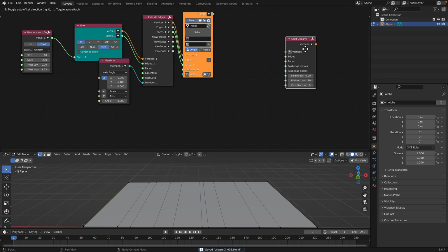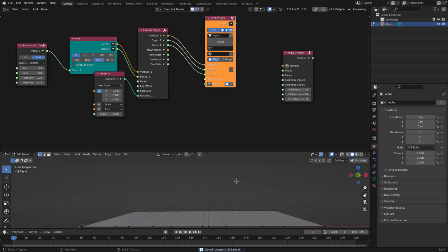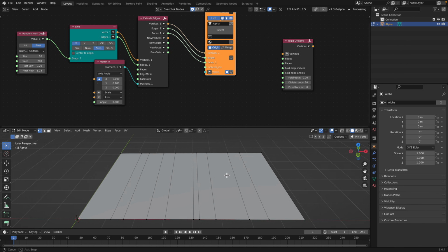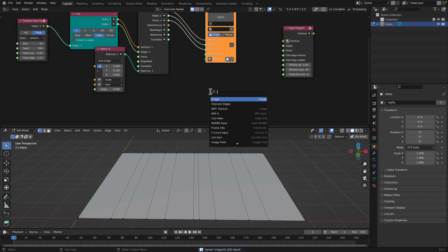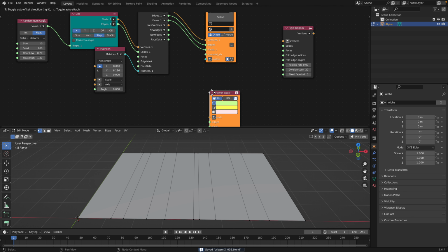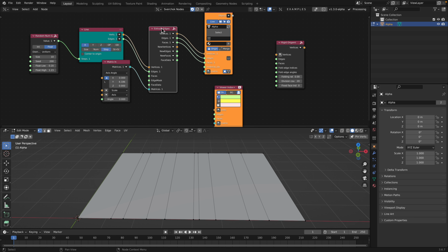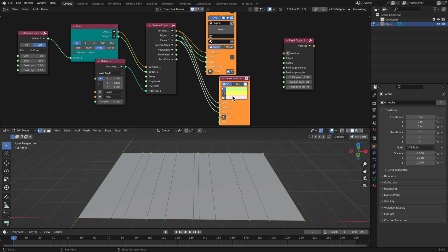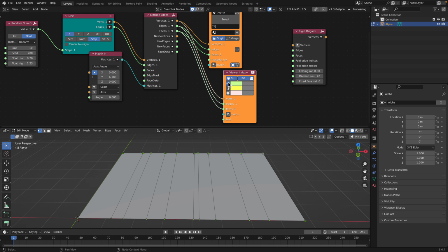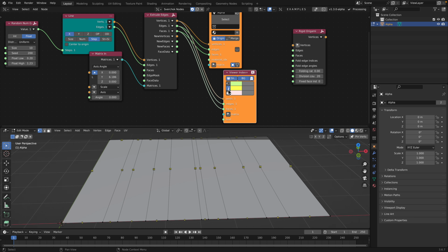So in order to make sense with the fold, first of all, we need to see the index where we want to fold the edges. So we use the index viewer node. Select this node, and then tap V, and then we turn on the background so it's clearer. We're gonna turn on the vertices and the face, or maybe just the edges and the face.